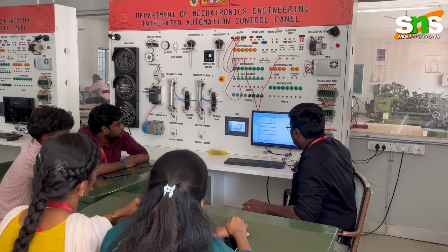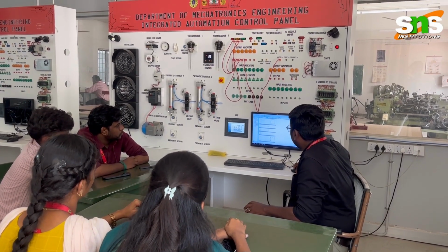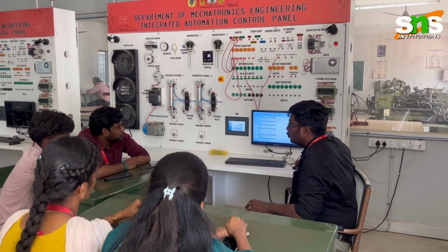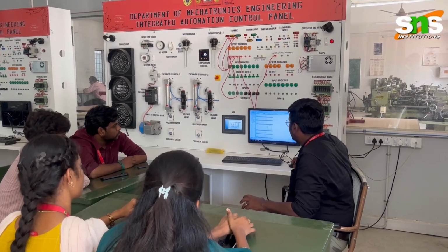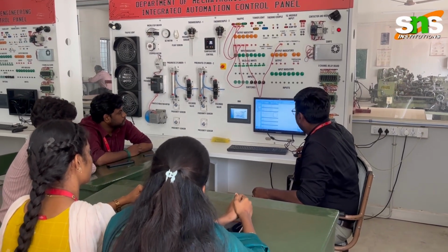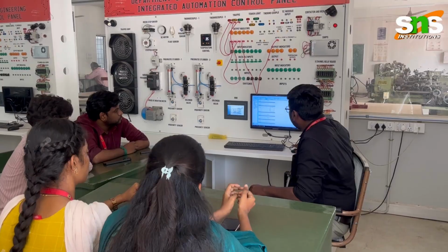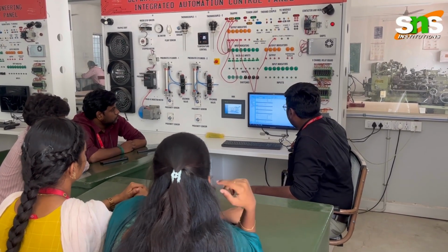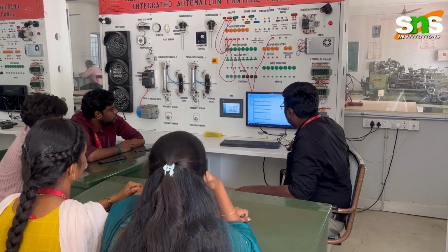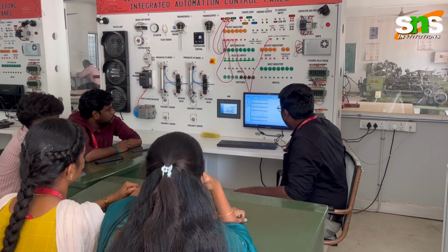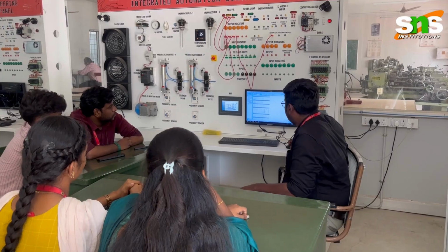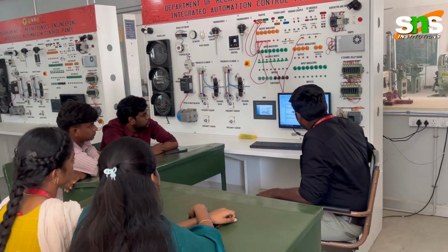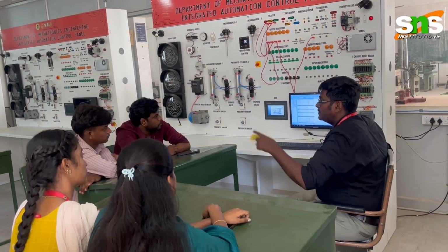That will be considered as M2. Then M2 will go to the output Y1. Then M2 will enable timer T1 for 50 milliseconds. Then the T1 value will automatically reset and be set for the next upcoming input. Then M3, the third virtual value, will be set to the third output Y2. Then the third output will be enabled for 50 milliseconds. Then it has to be reset to M3. After that, M1 will be set for the loop cycle.